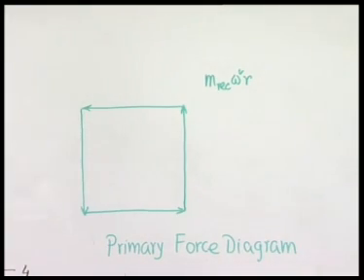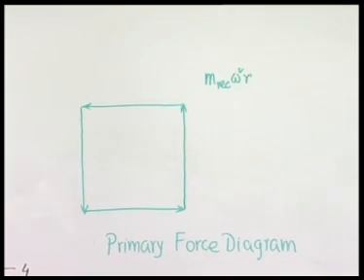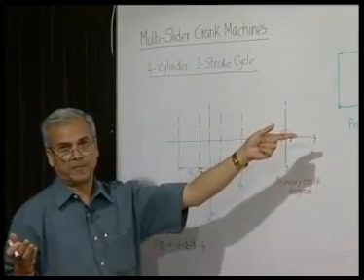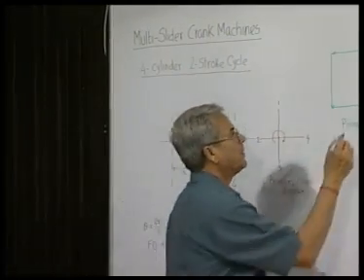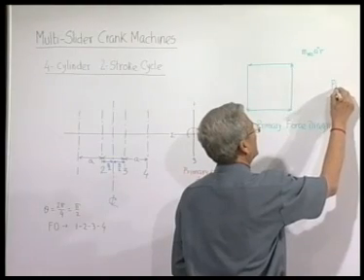As we have seen in rotary balancing cases, if there are m reciprocating placed at the crank pins, they produce 0 total resultant force in the whole engine, because the force vectors form a closed polygon. So, therefore, primary forces are balanced.